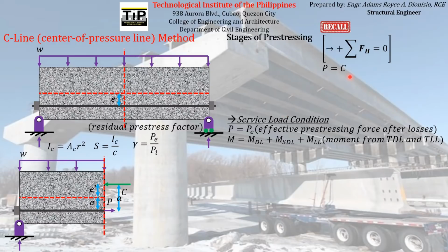So we have found out that the total compressive force is just equal to the pre-stressing force acting on the pre-stressing reinforcement, according to this equation that we solved using one of the equations of equilibrium from statics.